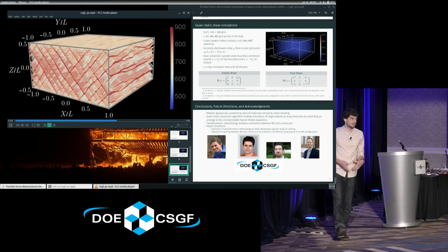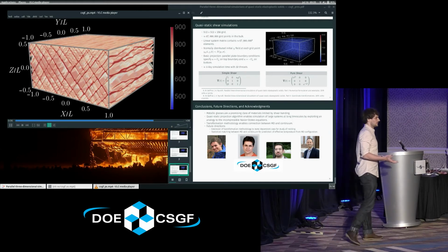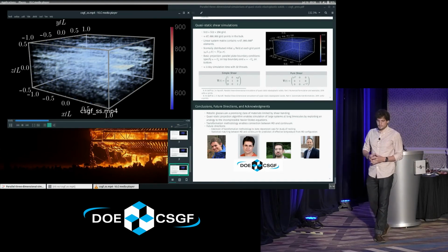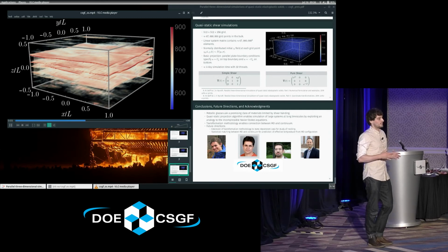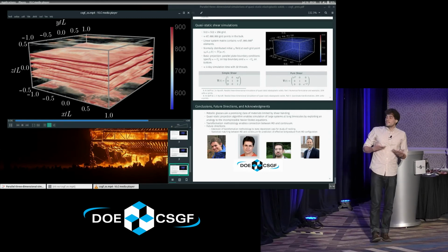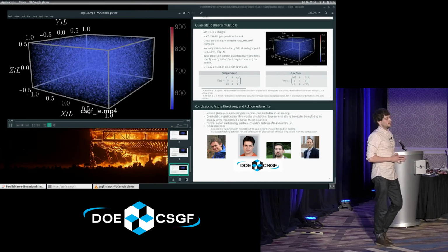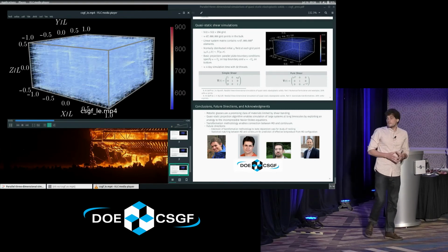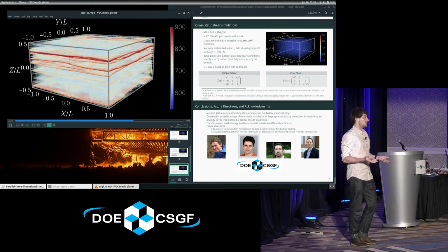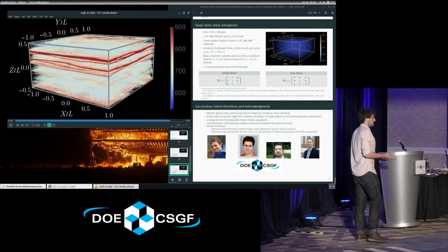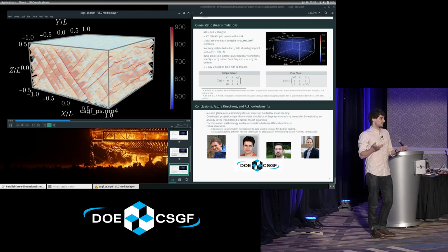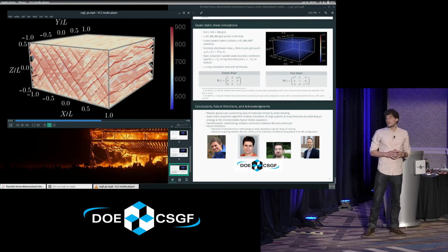As a conclusion, metallic glasses are a very promising new class of materials, but they're difficult to simulate using traditional methods. So we devised a new algorithm based on an analogy to the Navier-Stokes equations, which lets us simulate large system sizes and long times. And the transformation methodology enables us to connect MD simulations to continuum scale simulations. Future directions are actually performing this statistical matching procedure so we can compute the effective temperature from a given MD configuration, as well as extending the transformation methodology to the case where T depends on the local position. And in particular, we want to use this to study a necking instability in a stretched bar.